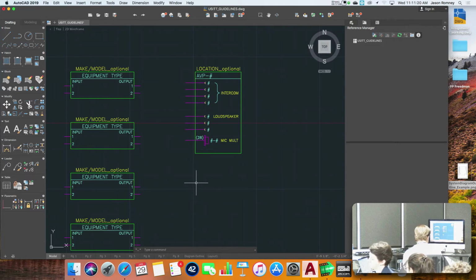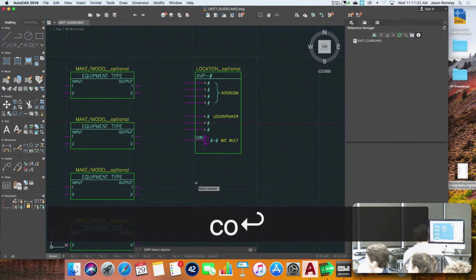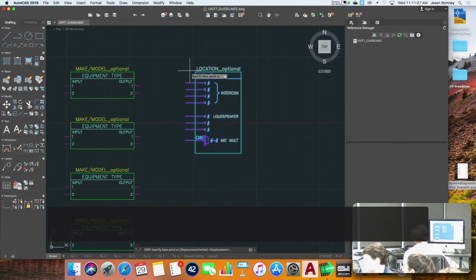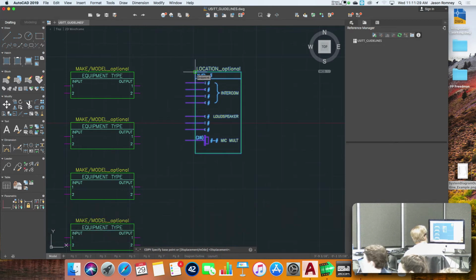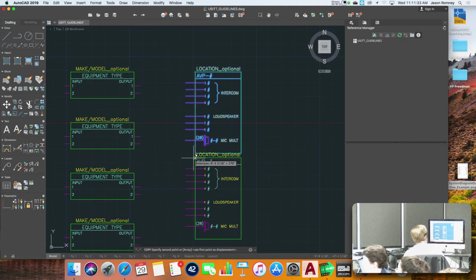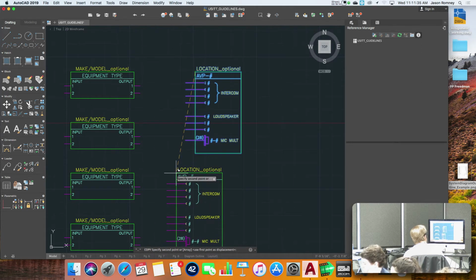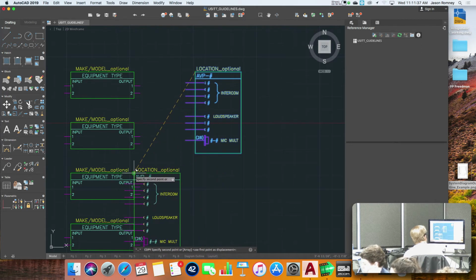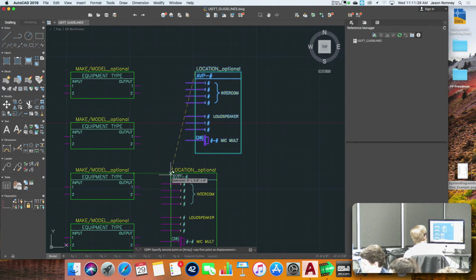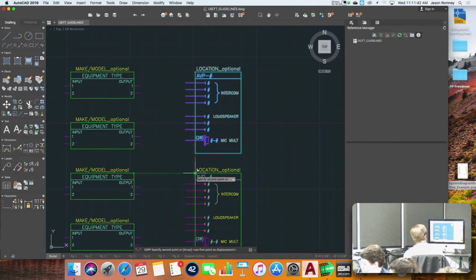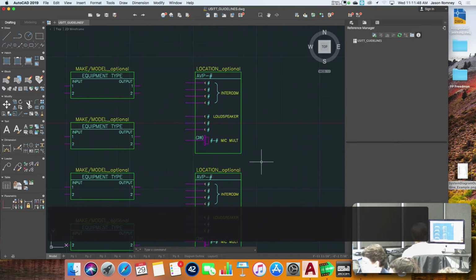So in this case, I'm going to copy. And I'm going to click at the top right corner again, track down from there. And while I'm tracking down from there, I'm going to go over and grab that top left point, track back from there, and see where it jumps there. And now it jumps to the spot where those two tracking points intersect.